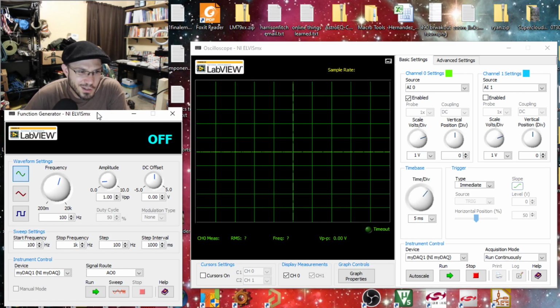And now let's turn this on. I'm going to set my frequency to be 1 kilohertz. 1 kilohertz is what we're going to be using in this next lab. So let's go ahead and change this. Oh, that's going to take forever if I use this box. I'm going to highlight the whole thing and I'm going to type 1000. Okay, that's 1K. And when I hit enter after I typed in 1000, it took that setting, and if you notice, the dial moved over here.